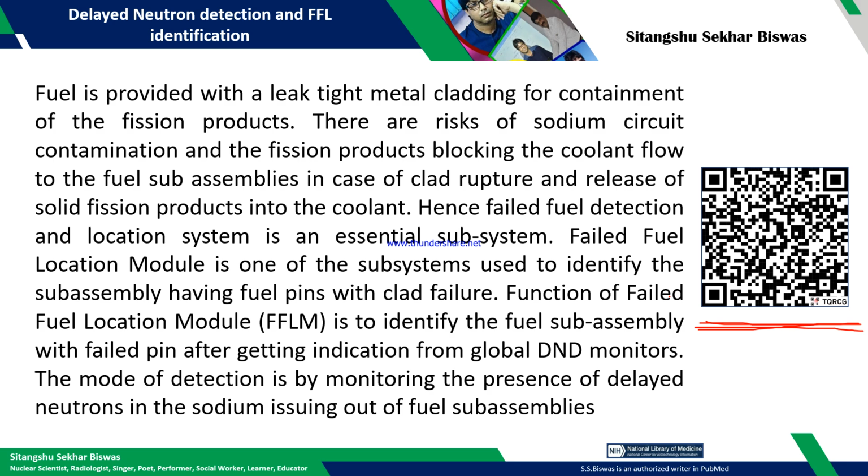If it comes out from the subassembly or the cladding, that fission product may block the coolant flow in the subassembly. So normally failed fuel means those fuel whose cladding of some of the pins is ruptured.